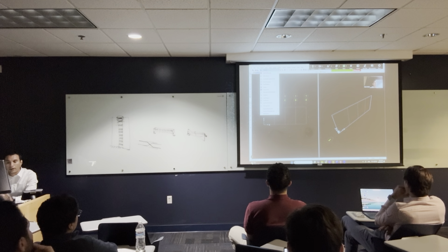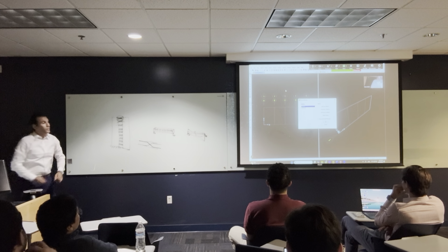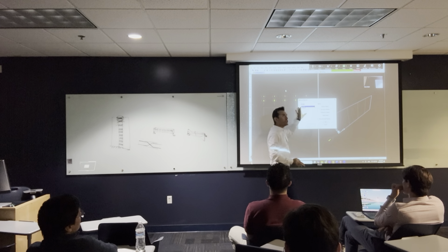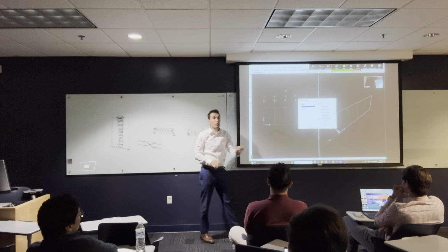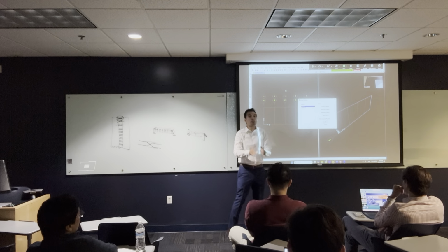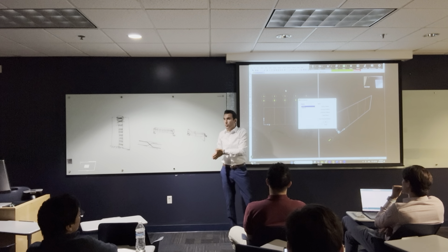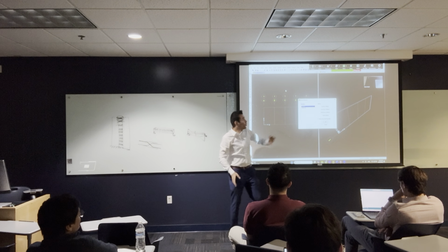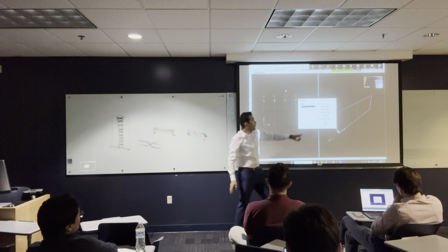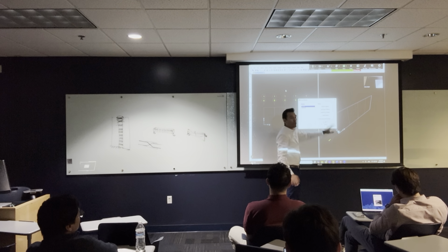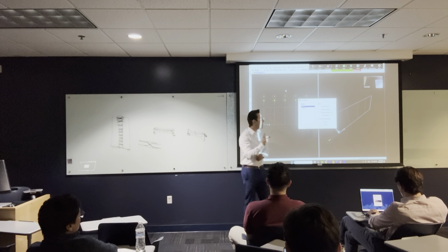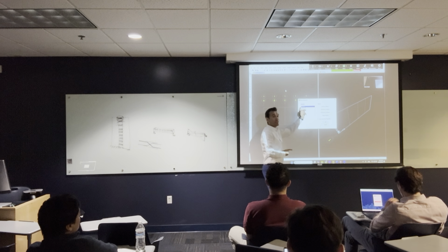Okay, let's just start by defining the materials. Once you start defining materials, you are going to find that SAP 2000 already has two materials predefined for you. You can use them. However, sometimes in some engineering projects, these materials don't represent the materials that we have in our project, so we have to redefine the material. You either modify them or define a whole new material, or you can import materials that you already have on file. Some companies have their own materials, and you can just import them.